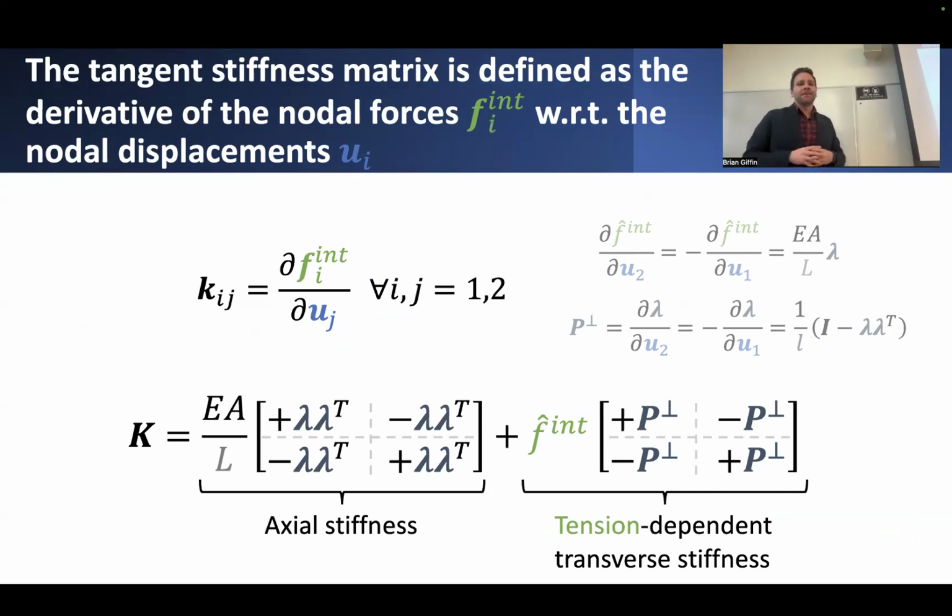of this element. The tangent stiffness matrix now has these terms that, as I said before, are consistent with those terms related to taking derivatives of f hat with respect to the displacements. You get something that looks kind of like this. And then there's those other terms that arise when you leave f hat alone in my product rule of differentiation, but now just take derivatives of lambda with respect to the displacements. You get this other term that involves f hat, which we left alone, that provides this additional stiffness term.